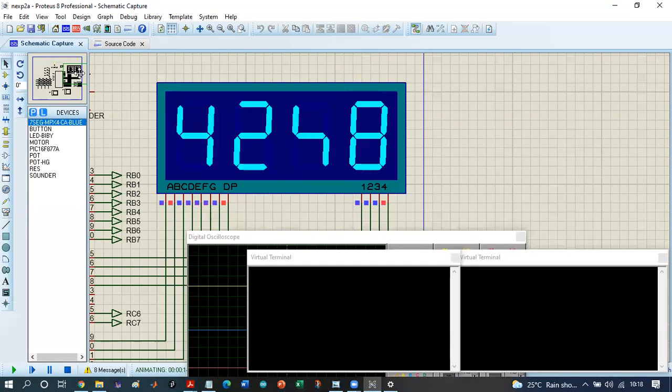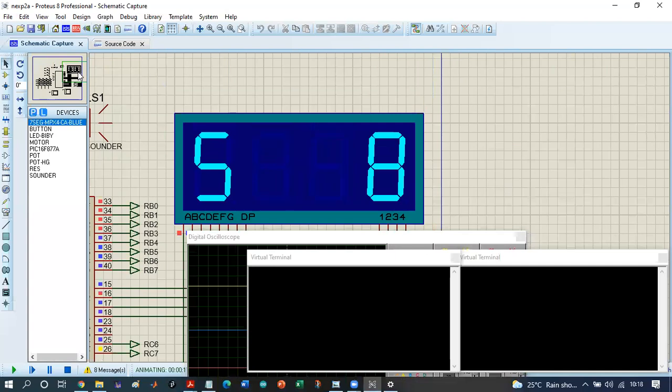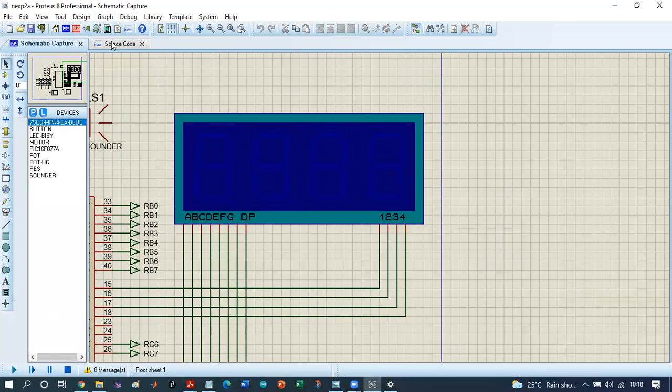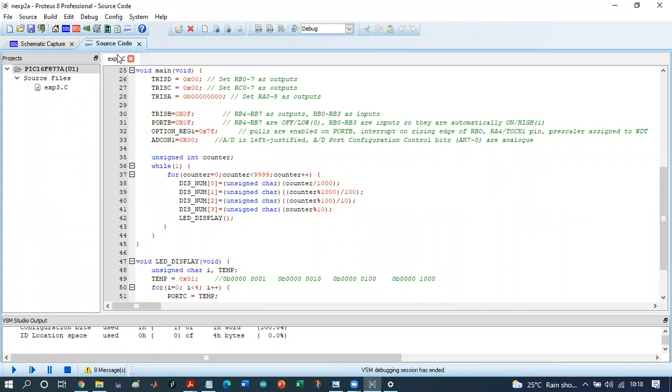But if we failed to put it inside the while 1 loop, then it's just going to run once. You will not even know when it runs, because 4 megahertz is a very fast speed. So your code will not even appear to work. If it runs at very fast, speed of light, you will not know when it's run and finished. So that's why the while 1 loop is important. Even that first code we did, where we were pressing buttons and changing the display of the 7 segments, even that was in a while 1 loop.